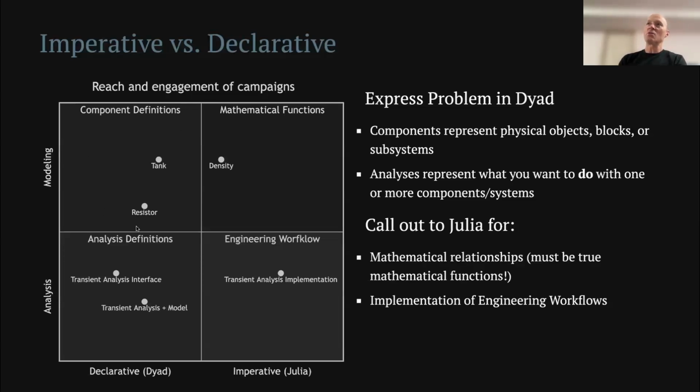What that means is that we have the ability to have somebody build a model up here, describe all the entities and their relationships and connect them up here, describe the mathematical relationships, for example, the fluid properties here, and then pass us that symbolic representation and do something with it. So we might run a transient analysis, we might run a steady state analysis, we might linearize it. But the point is, because we have this step where we can get access to the symbolic representation, there's a whole bunch of things we can do, and it's extensible.